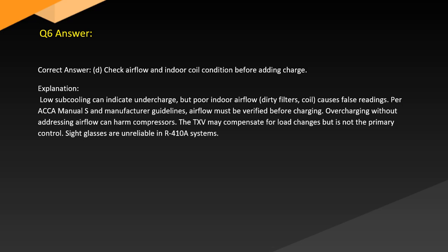The TXV may compensate for load changes, but is not the primary control. Sight glasses are unreliable in R-410A systems.